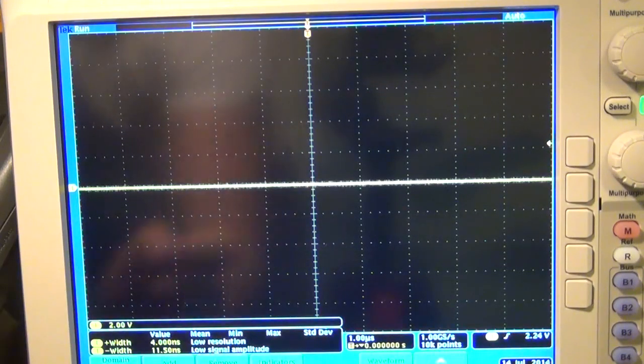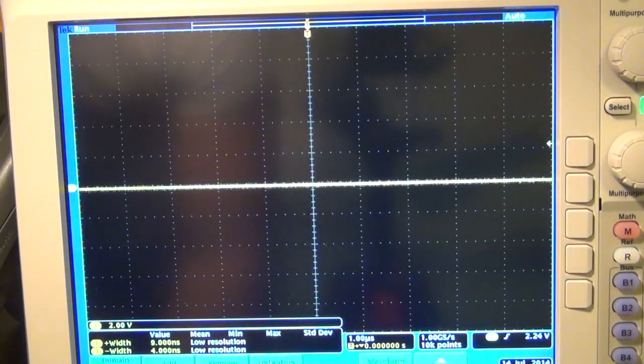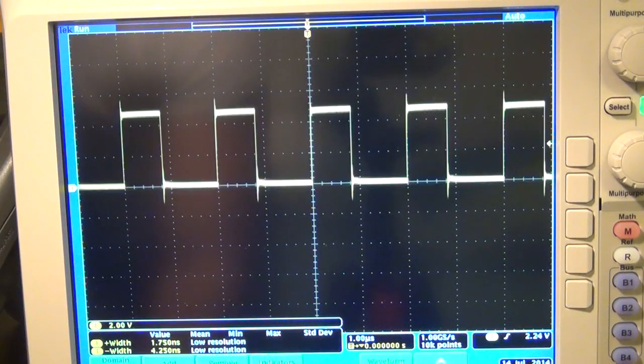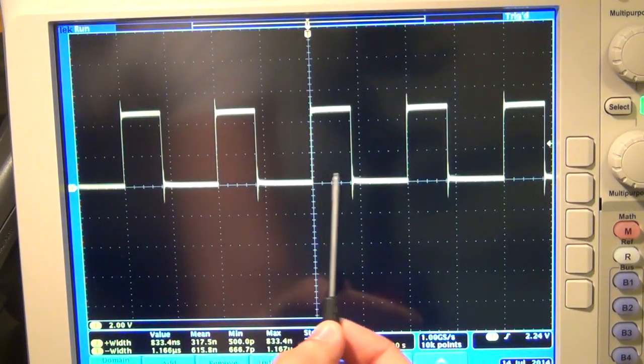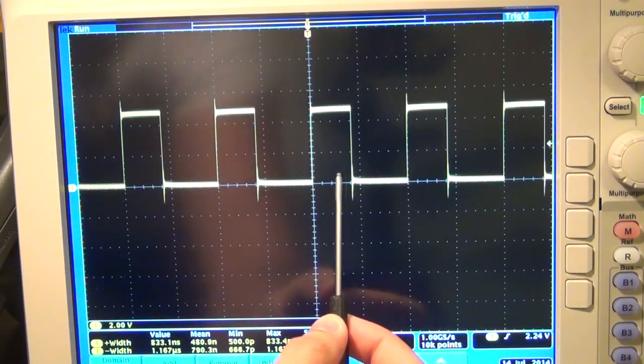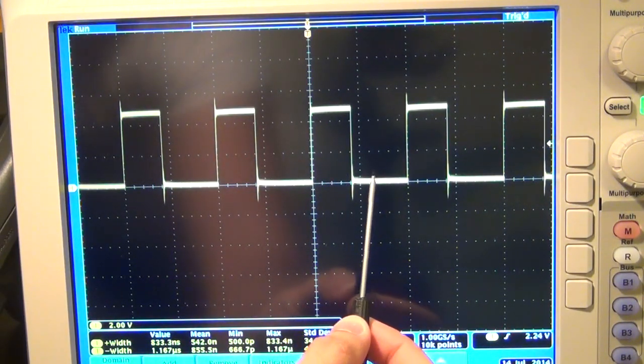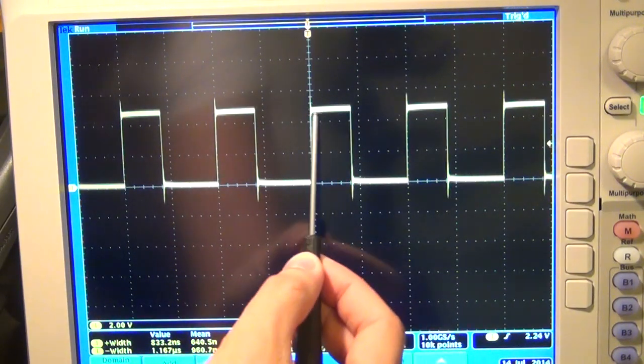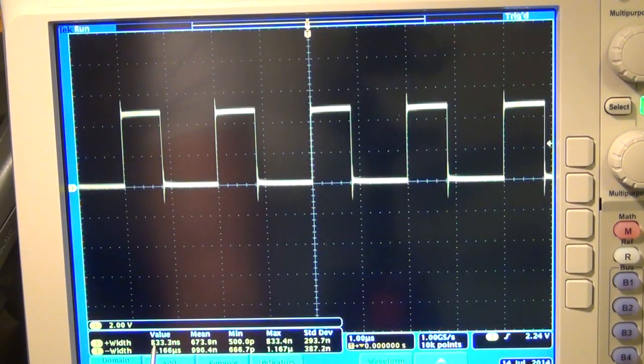So this waveform should disappear and then it will come back, and then you will see that the order is reversed. Here we go. Now I have long periods of ones and then again a very short period of 0. I cannot meet the 0. Now this 0 should be 0.4 microsecond, but it's not. But I'm meeting the high. The width of the high should be 800 nanoseconds or 0.8 microsecond, and it is.